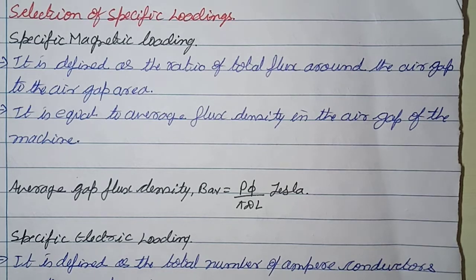And the gap, if it is too much, since this air gap is also part of the magnetic circuit, the higher the air gap, the leakage will be more, that is the flux linking will reduce. So care has to be taken, and also we cannot make it 0, which will make the basic principles itself a false one.